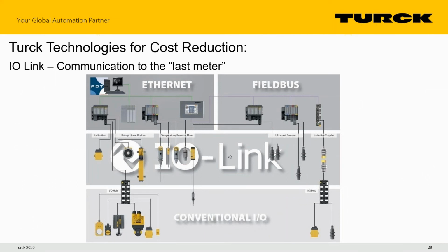So if you've heard the terms Industry 4.0 or Industrial Internet of Things, IO-Link plays into that, because those two concepts, that's one concept with the same name, is all about getting more data back. So in the upper left here, we have our control system, our SCADAs, our DCSs, things like that, some of which may have IO-Link masters directly associated with them.